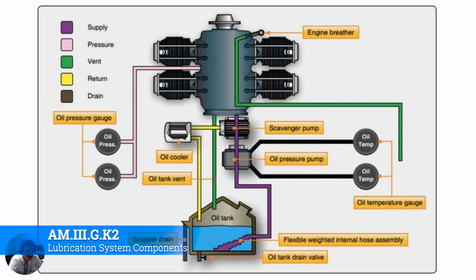Then you have your oil pressure gauge, which will tell you where your oil pressure is at. A rule of thumb with troubleshooting is that high engine oil temperature usually indicates a low engine oil quantity, and you should see a drop in pressure as well, depending on the system. You don't want high engine oil pressure because everything has limits, so if you over-pressurize the system, boom, something could fail.